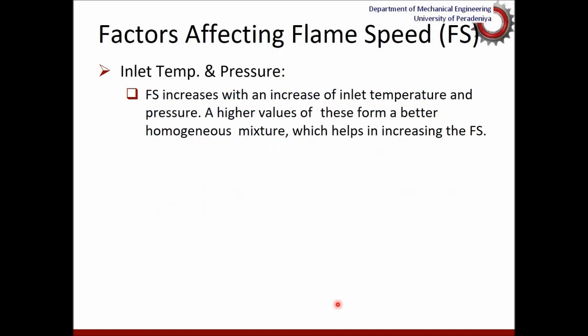And as I just mentioned, the temperature and the pressure during the combustion process have a greater influence on the flame speed. The higher the pressure and temperature, the quicker the burning is, the higher the flame speed is. Then the temperature and the pressure all throughout the engine process inside the cylinder depend on the pressure and temperature at the very beginning of the engine cycle, that is temperature and pressure at the intake. So if the pressure and temperature are high at intake, then again you could expect fast burning or high flame speed.